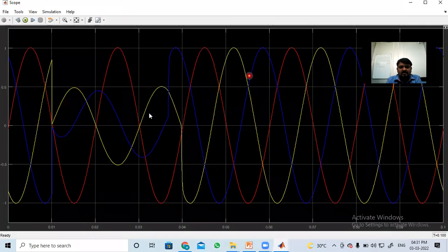What we have, see here now. At 1, I have created a fault. The switching time of the fault is 0.01. At 0.01, the phase was at the negative side. Suddenly it went to 0, and some voltage has dropped here now. And for up to 0.3 cycle it is reduced, and after that the fault is cleared, it is going to come normal. Same for phase B also here now.